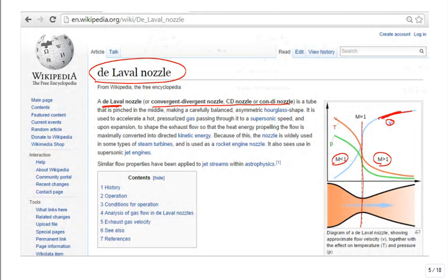What about the temperature? Drops, because energy is still conserved, isn't it? So enthalpy plus kinetic energy is equal to a constant. What about the pressure? Well, the pressure is high, pushing it through the nozzle. And then what you exit at is typically some sort of ambient pressure.